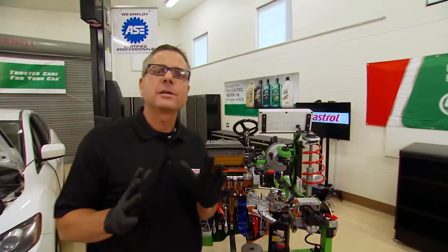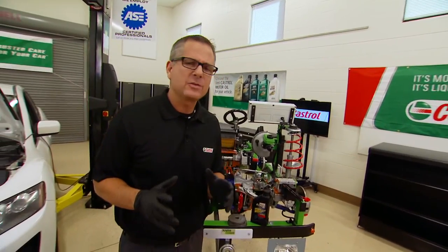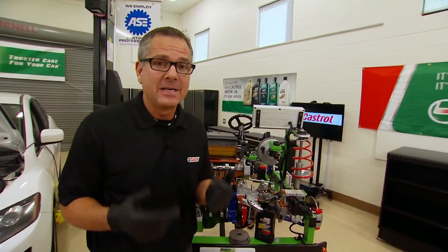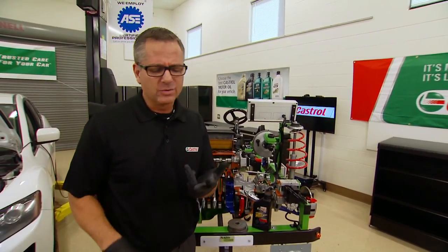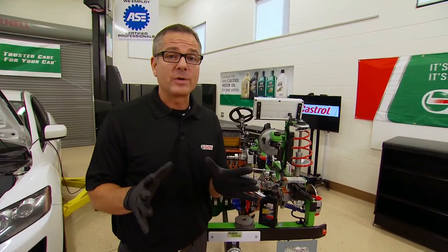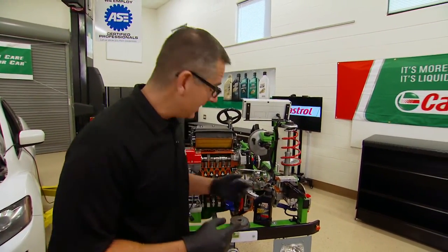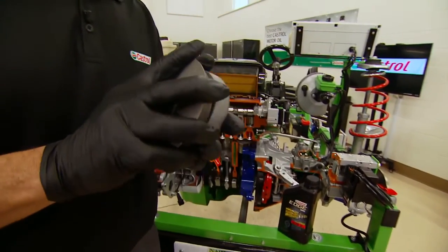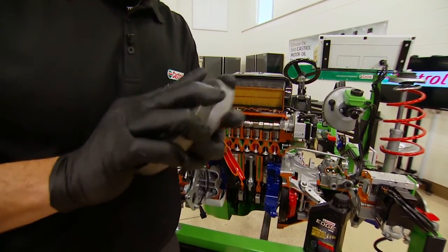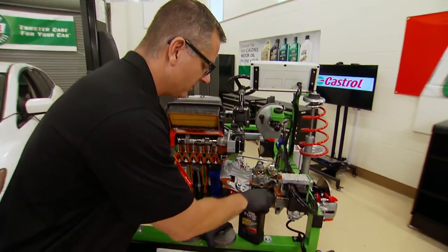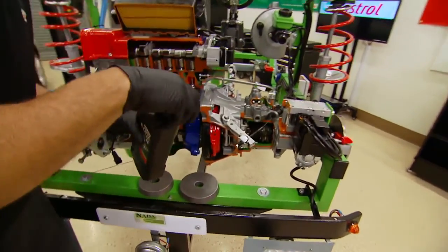All right, let's take a look at the motor oil basics. This will help you serve your customers with confidence because you'll know exactly what it does. Now, motor oil cleans, cools, protects, lubricates an engine, but I think it's more important if we take a look at it in action. And I got a couple steel plates right here. What if I take these steel plates and I simply just rub them together? You can hear them grinding. Because what oil does, it creates a film. It creates a film in between all these moving parts in this engine here.